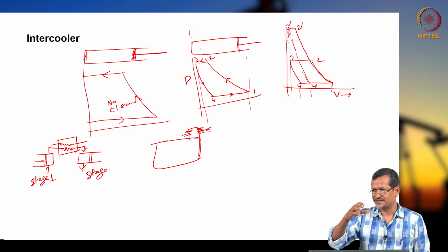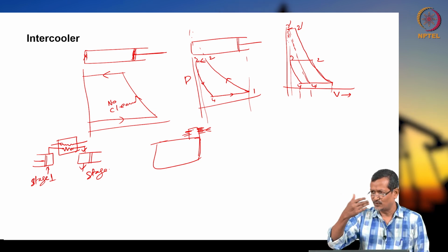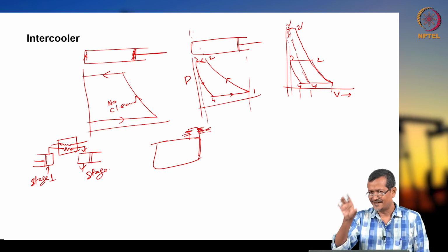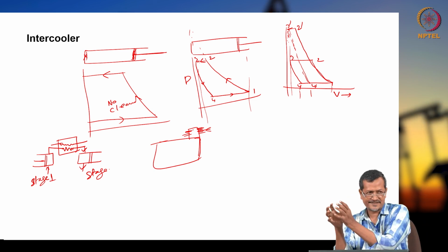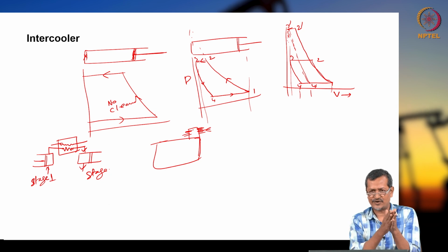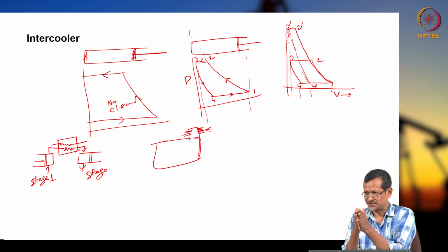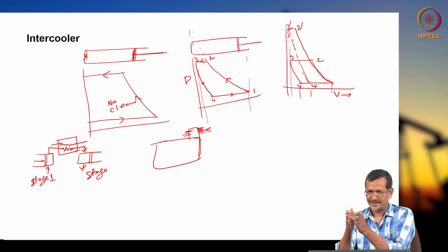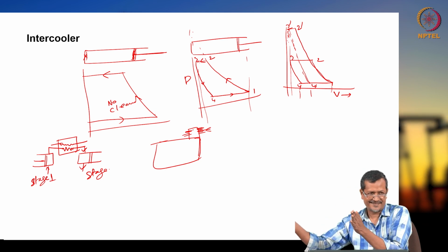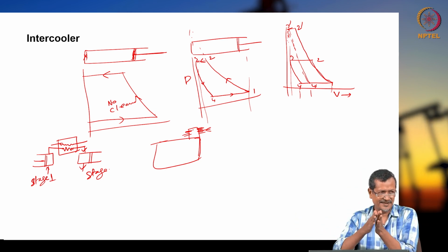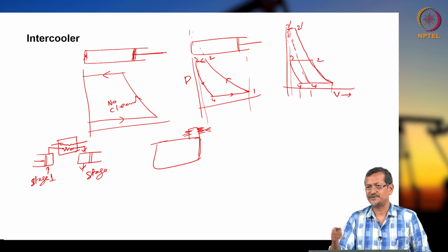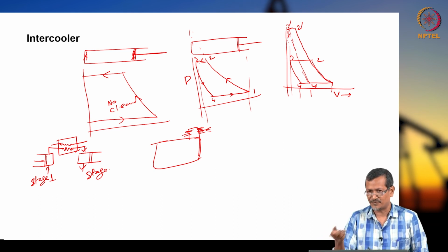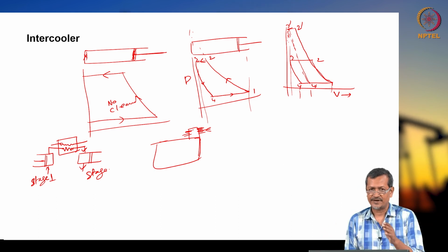So one cylinder compressing, intercooler will be there, intercooler means cooling the air, then put that same compressed air into another cylinder, again compress. So 1 to 5 bar you increase pressure, reduce temperature, again 5 bar to 10 bar maybe, instead of going to a single compression system. Single compression means it will be taking more energy and performance will be lower. So they will be putting an intercooler.